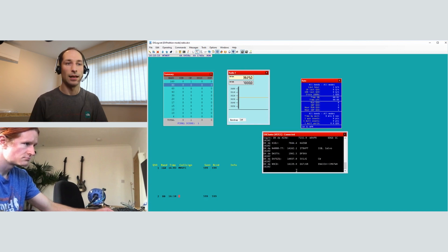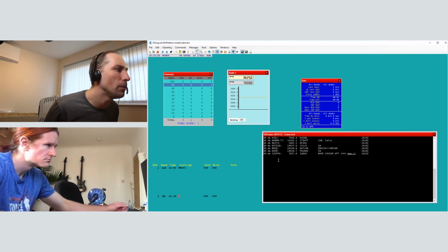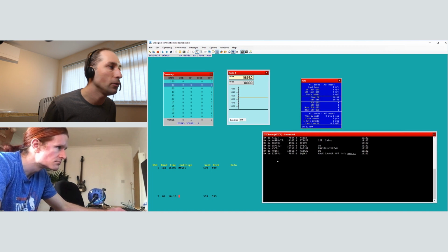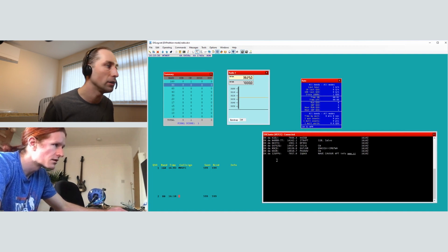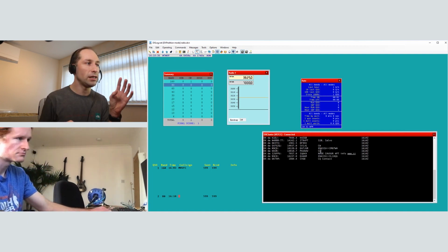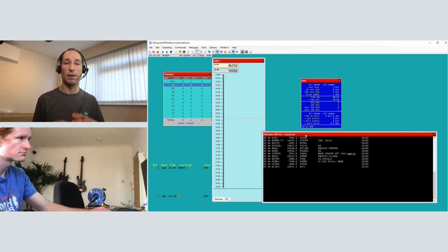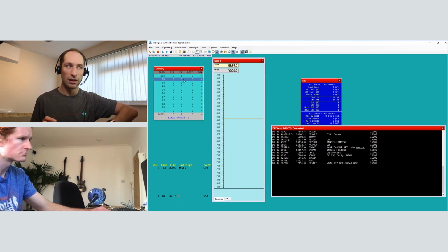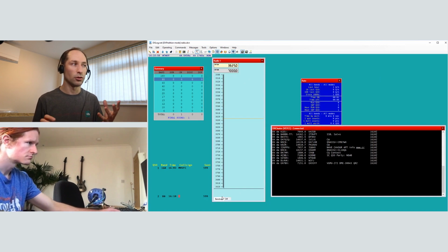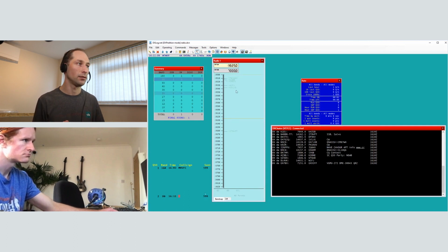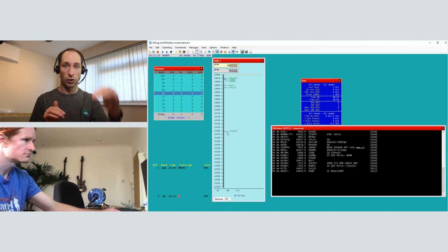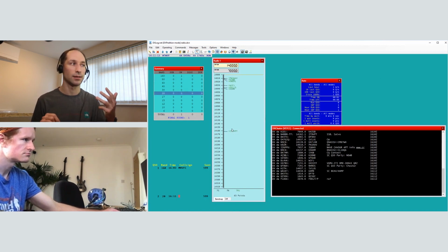So that you can now see coming into there, there's what we call spots. This is indications that one station, in this case IZ6PPU, has spotted IQ6XX on a frequency of 7057. On that Radio 1 panel, that's showing you a band map. So that's showing you the sort of surrounding frequencies and a list of stations on those frequencies. There's probably not a lot going on 80 meters at this time of day in Europe. But if you go on to, let's say, 20 meters, you now see that there are stations showing up on the band map. Those are coming from the DX cluster.